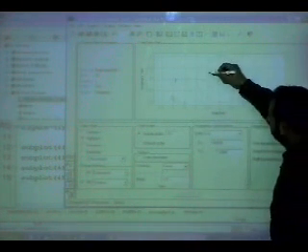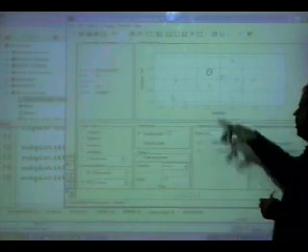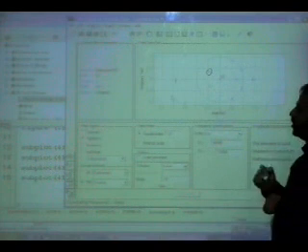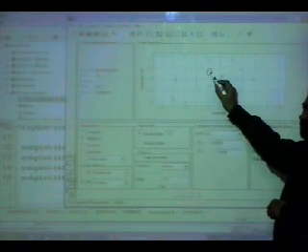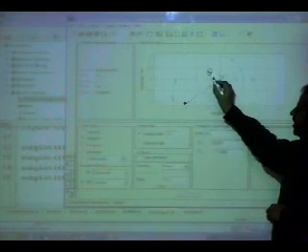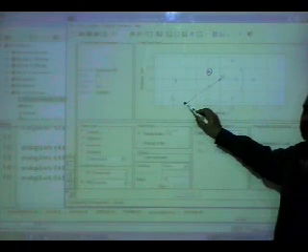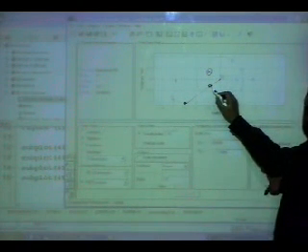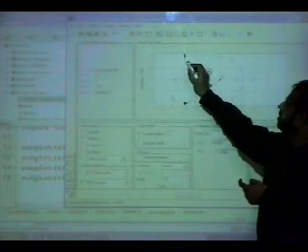So whenever we are designing a linear phase FIR filter, at least if, for example, I give you a question in exam, you only know this. Can you plot other 3 zeros? Yes, you can. Okay, so for this, first zero will be here. For this, a zero here to make it linear phase. Then to make it real, you need to place a zero here. And to make this zero linear phase, you need to make a zero here. So you know this. If I tell you it is also type 2, then what?